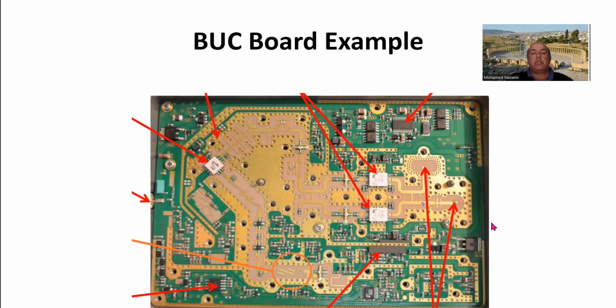The DC in this design here, this is probably a 10 watt or 15 watt or 20 watts at most, I would say, unless it's really down in the 5-6 watts. Although there are two power amplifier GaAs FET devices. This is a previous generation. You might say this is like 10 years old. So the devices used then are all GaAs FETs, okay? And here's the mixer in here.